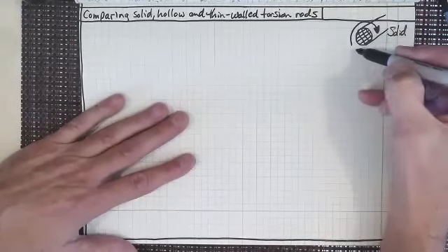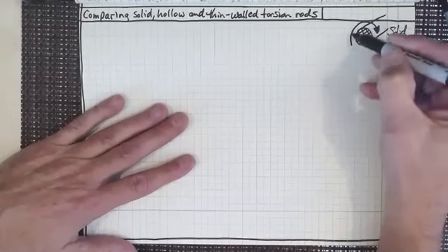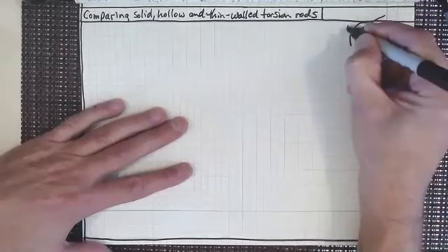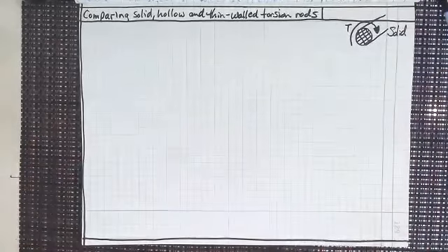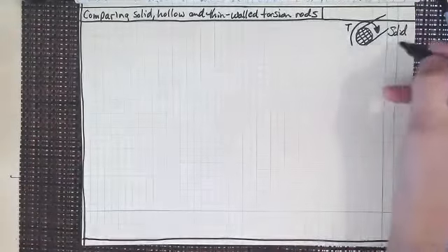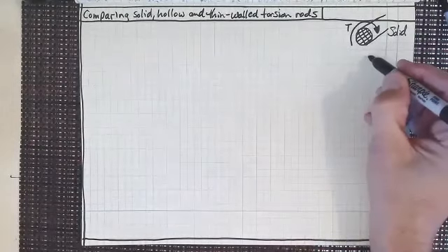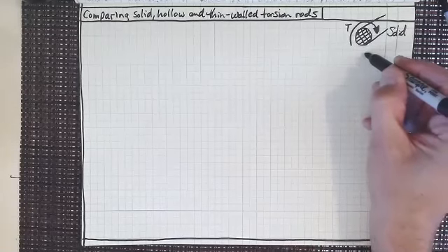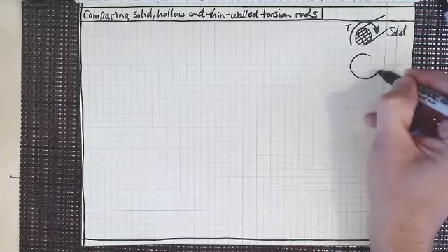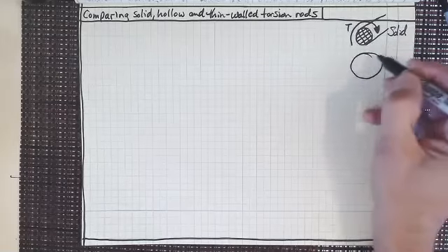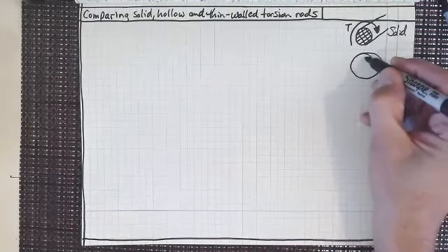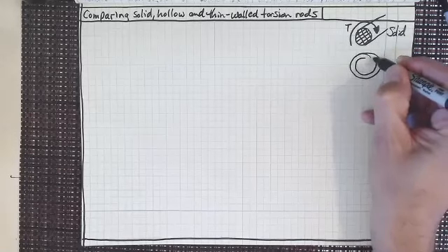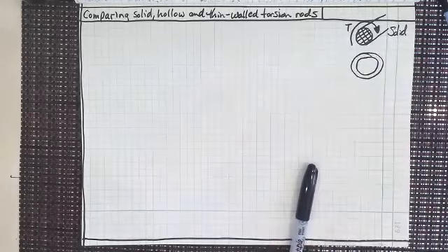Right, so there are the torsion rods, or rods in general, that are under a torque loading, right? This is our torque loading. They are in pure shear, whether it's a solid or, now to carry that same torque, I would have to have a larger hollow. I'm going to draw it like that. That wasn't very good. I'll try and clean that up. I'm going to have a hollow torsion rod. Why would I want to do that?